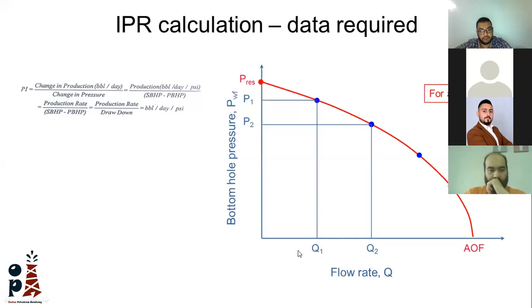Using this value and this permeability, and the unconfined compressive strength, we can know this value from sonic logs. So you know these values and you enter certain diagrams and they tell you that if you exceed a certain drawdown, you will have sand production.